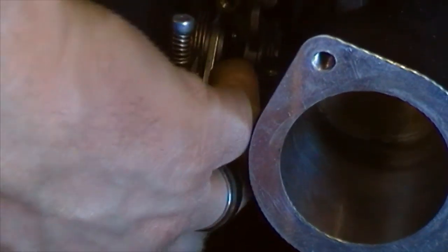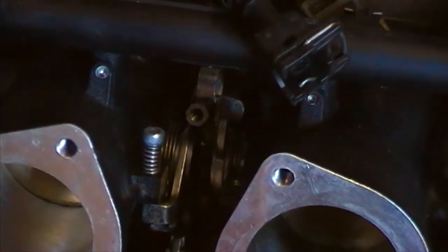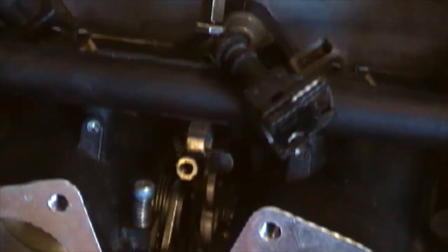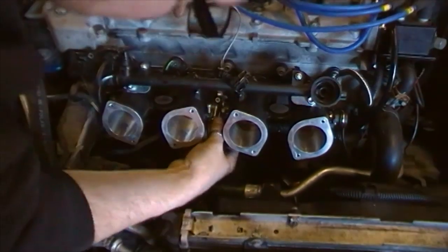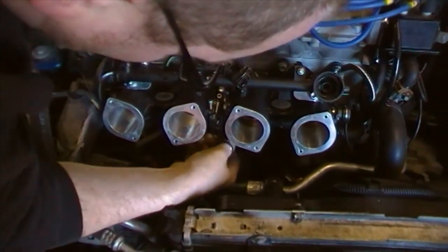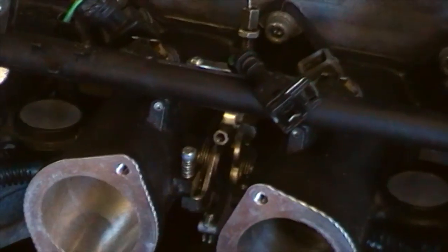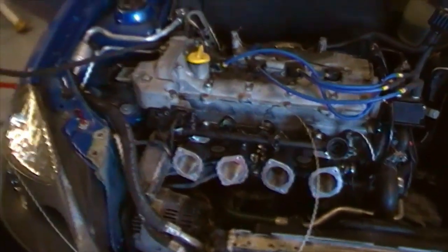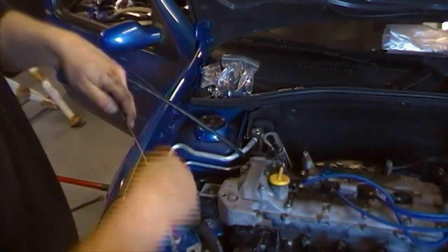What we can do now is get all the way to the other end of the cable and feed that up through the adjuster, which we've just bolted on very carefully so as not to damage the end. Pull that through. Guiding it round the linkage itself, and now that operates correctly. What we can now do is slide the inner cable inside the outer cable, again being careful not to fray the end, all the way down.